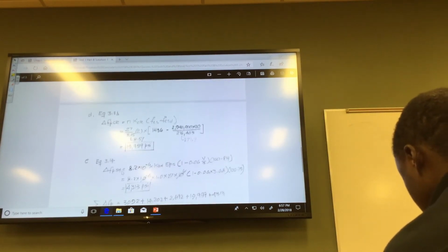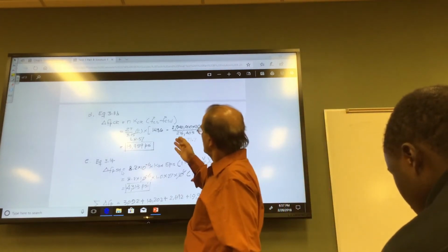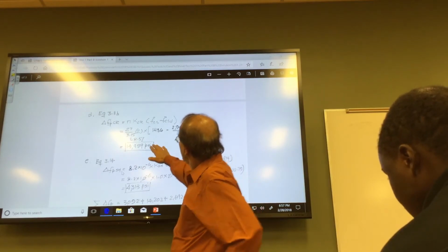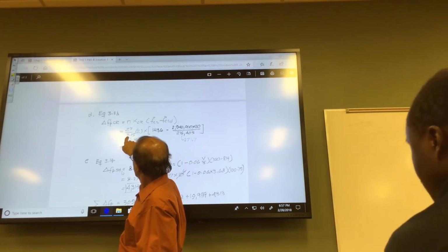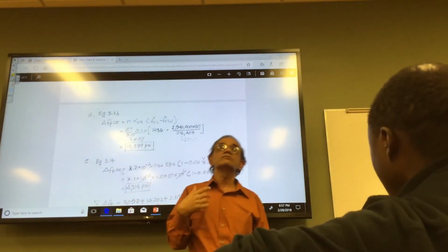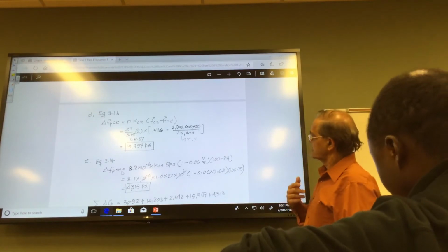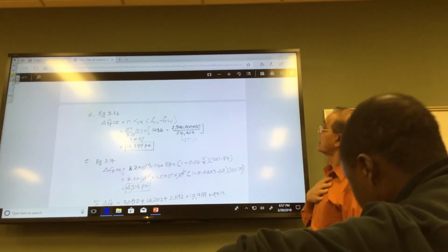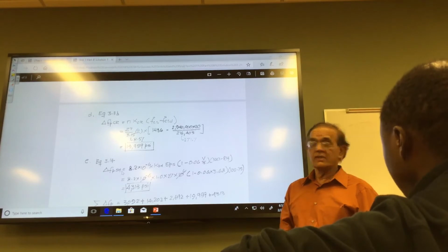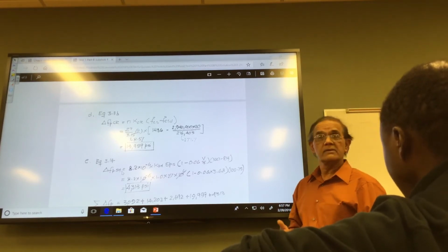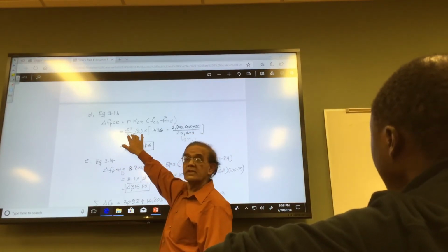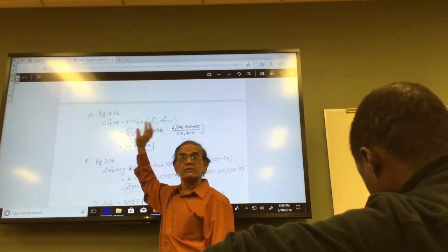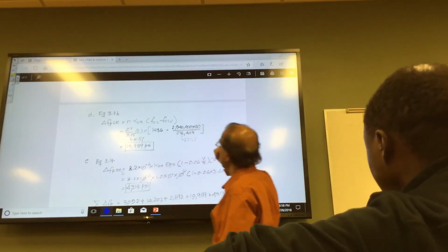Then equations D and E are very simple. D is for the creep, and so N is the ratio again, but this time this EC is the EC for the final value, because creep is a long-term phenomenon, so you don't want to use the initial ECI, right? You want to use the normal EC, which is a higher value. So if you didn't do that, then you're not following through what we are doing here. So make sure this is the condition.